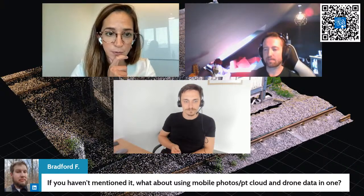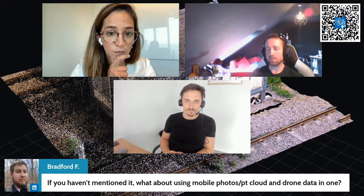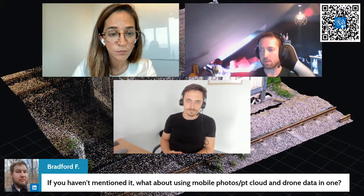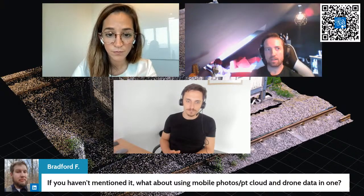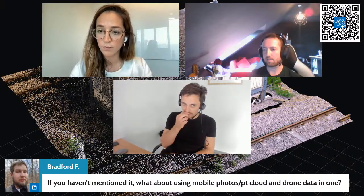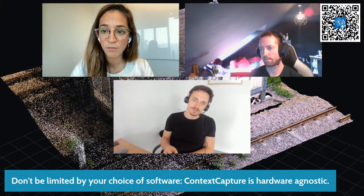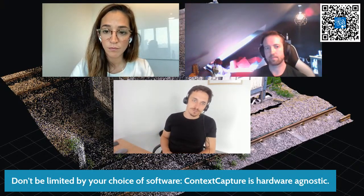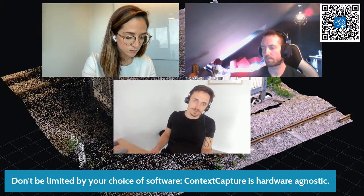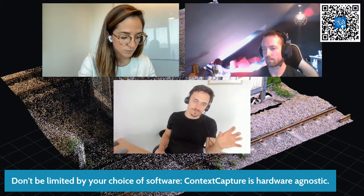So it's absolutely possible to combine all these data sources in one 3D mesh, both indoors and outdoors, depending on how your project is set up. We have plenty of the basis for those digital twins that are both outdoor and indoor. Everything is based on our tie points, as you set them on the pictures, or you will use ground control points, for example, together with a surveyor, which I always recommend at some point, because then you can create an independent source of survey control with the total station.